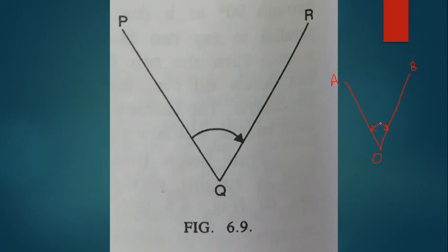Once the ranging rod at B is exactly bisected, we have completed the first repetition. Here I need to note down the reading on my vernier A as well as vernier B. I think we are familiarized by this time with how to measure the reading on vernier A as well as vernier B. I just remind once again.